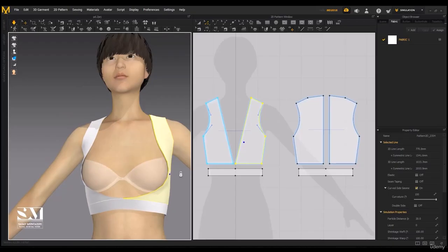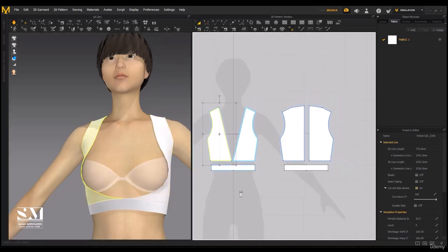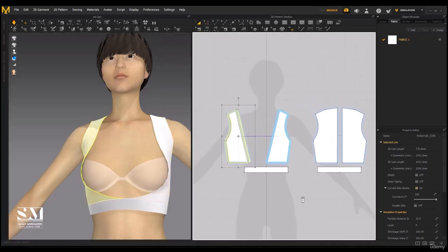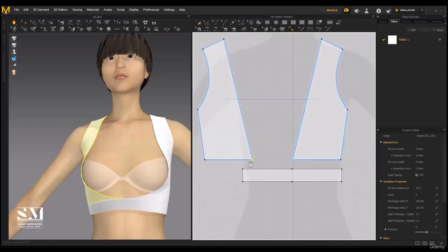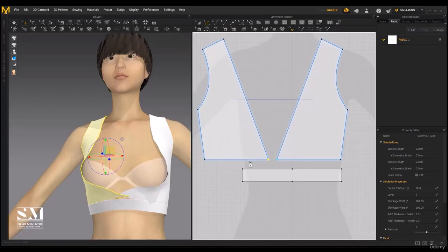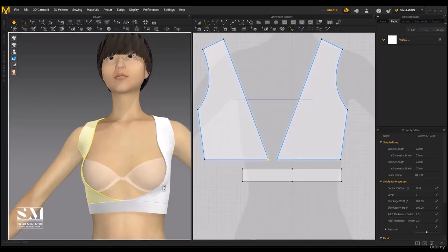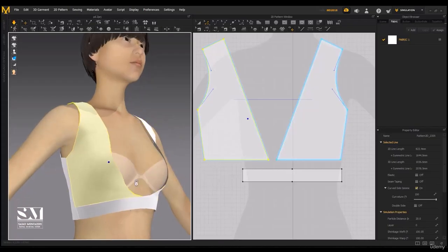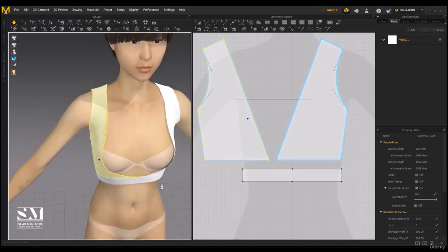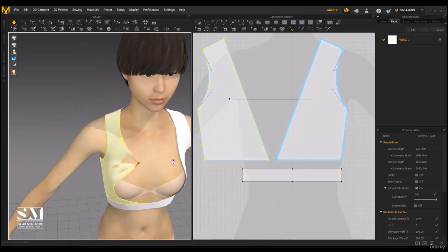If this method doesn't solve your issue as you'd like, you'll either need to increase the particle distance or enlarge the garment. How do we enlarge it actually? That's a question. Simply select one of these points and move it several steps left or right. In this way, we can enlarge it. Then select the shared point and border and move them rightward. This essentially brings the pieces closer together. Here you can do this, press space, and now the issue in this section is somewhat improved.